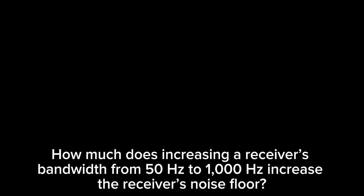What does a receiver noise floor of -174 dBm represent? B. The theoretical noise in a 1 Hz bandwidth at the input of a perfect receiver at room temperature. How much does increasing a receiver's bandwidth from 50 Hz to 1000 Hz increase the receiver's noise floor? D. 13 decibels.